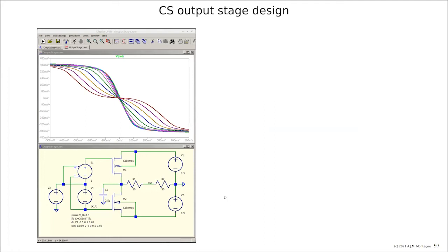And here you see, I think you remember we did this, the files are available. We made an output stage, we biased it, we designed 2 transistors, and we checked the characteristic, and people did it in various ways. This is only static. You also need to do it dynamic. This 2.5 pF represents the feedback capacitance, which can be considered in parallel with the signal path. So that is basically the test setup, the test bench for the output stage.